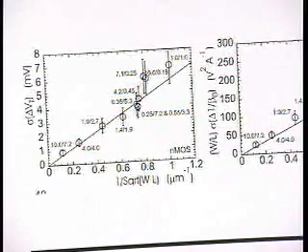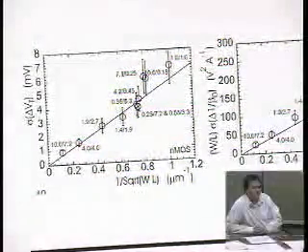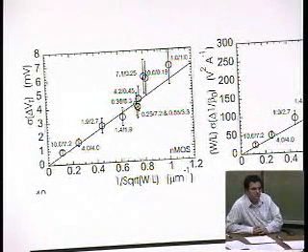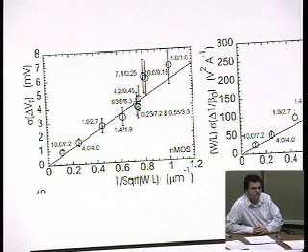Anybody? Drew, do you have any comments about matching? Well, I don't remember offhand the numbers that I've seen for absolute VT mismatch, but I think these days we don't consider T-ox variation to be much of a concern, and I think that more generally speaking, we consider VT variation to be more of a problem, though I'm not sure if the absolute numbers are bigger. And that's mostly due to dopant fluctuations.